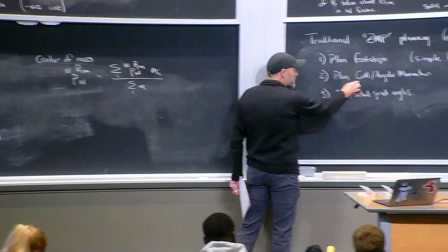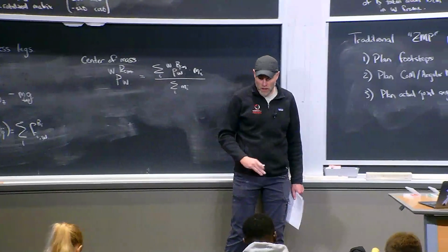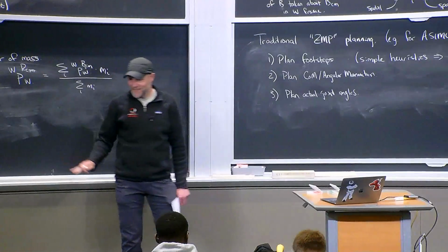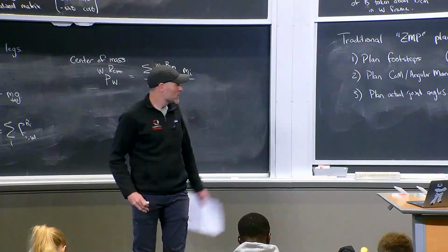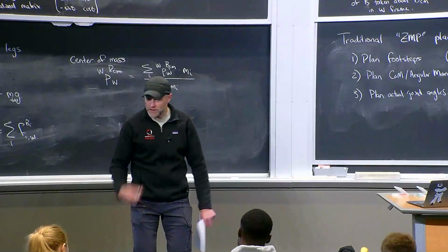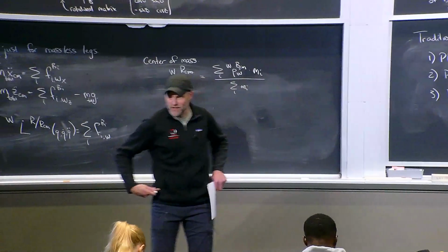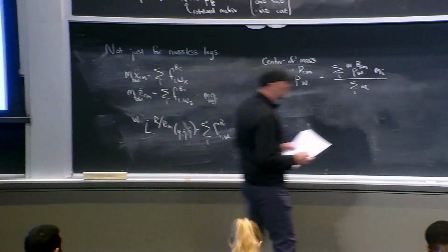The center of mass and angular momentum, because these equations become very simple, there are some cases closed form solutions to go from footstep planning with some restrictions, and then there's optimization-based ways to do this. Okay, and the last step is actually fairly simple. It's just solving kinematics problems to turn your foot position and your center of mass position into new foot positions.